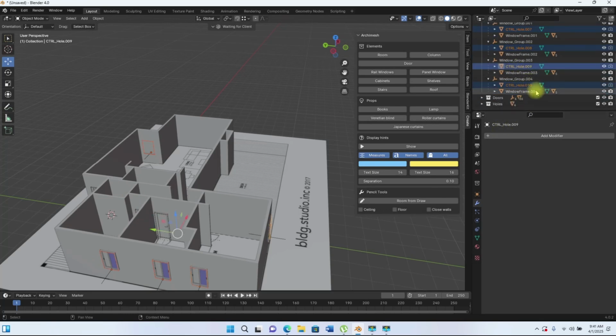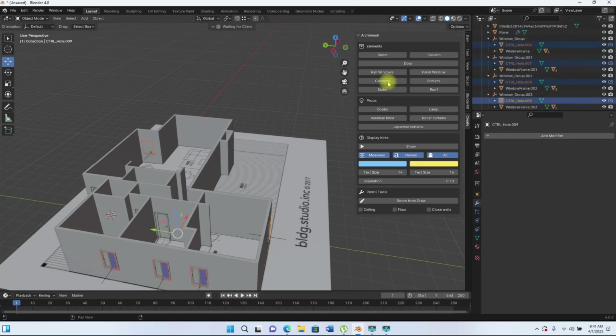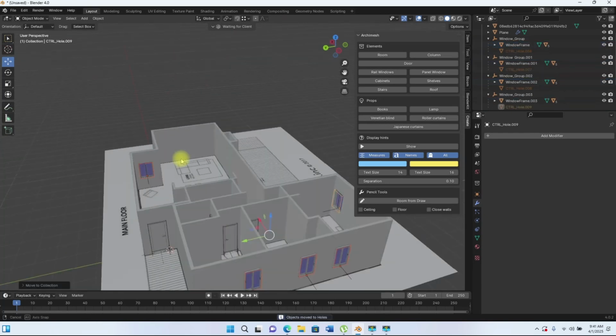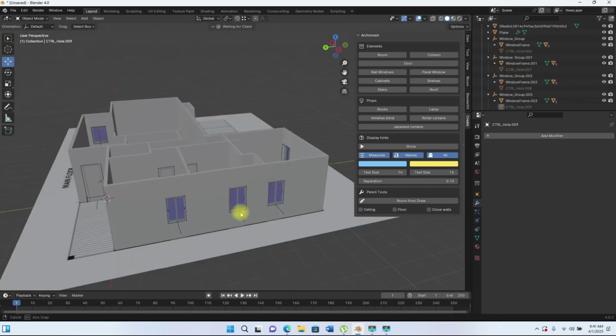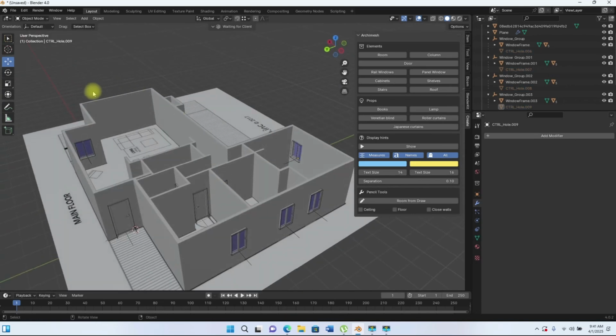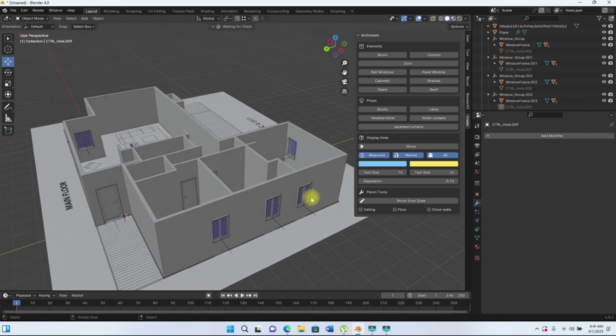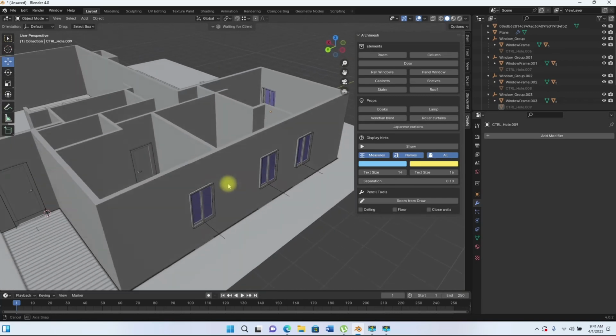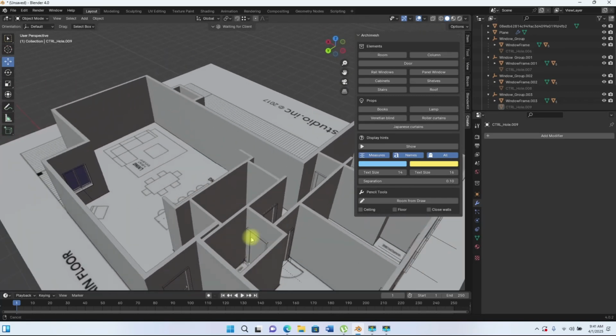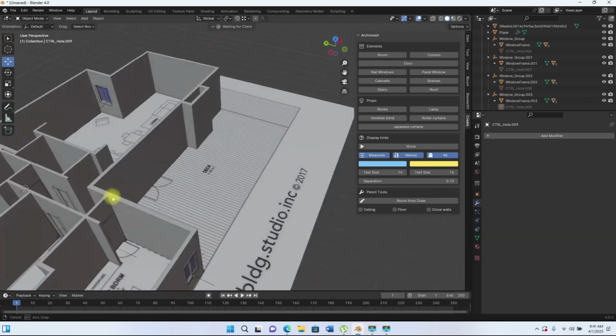So now we have all of these control holes selected, and then come to M, put them in the holes. Once we do that, it will automatically create the opening. So you see that I really do not need to create a separate hole since we are running the same operation on these. So for every hole control that I have, I'm just going to be putting them into those control holes and then it will cut through for this.